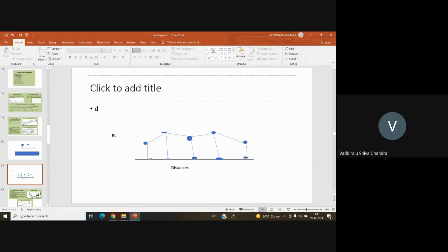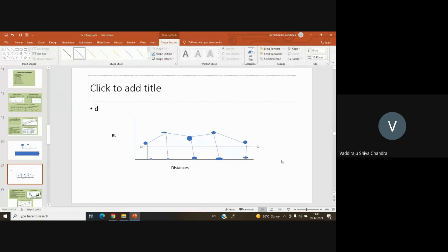And on this, if I overlay my design RL, let's say 200 meters, I want to lay a road at 200 meters from the mean sea level. So this horizontal line is 200 meters, let's assume. Then in order to lay this road, I need to excavate this top portion, right? So I can analyze the volume of earthwork I need to excavate, and I can do the corresponding cost management, etc. That is the purpose of profile leveling, or longitudinal leveling.